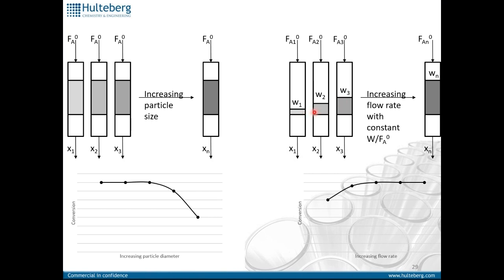And if you do this for several flow to catalyst volume ratios, you can get the same type of plot. But here we have at a low flow rate, we get a certain conversion, increasing the flow rate and the catalyst volume. So the same relationship still gives you a higher conversion. Then you know that you had a gradient. And again, doing this repeatedly until you do not see an increase in the conversion gives you an easy diagnostic test to prove that you're actually working without a gradient or outer gradient in this case.